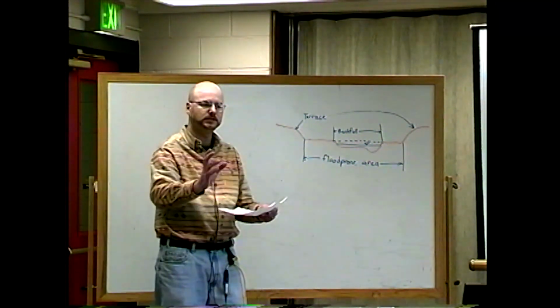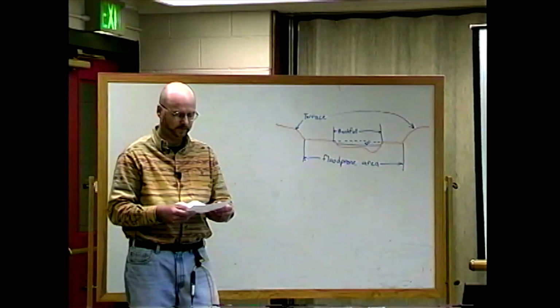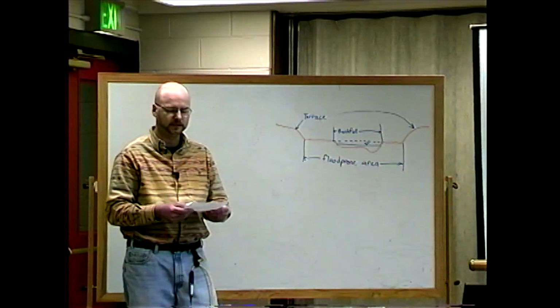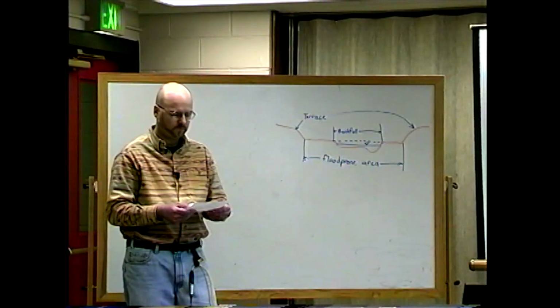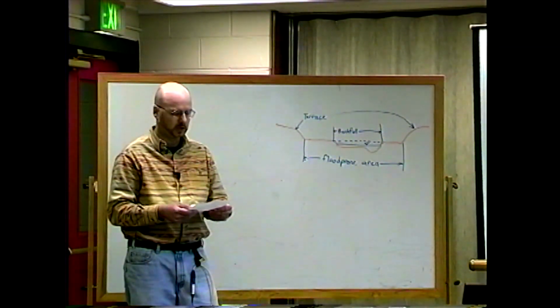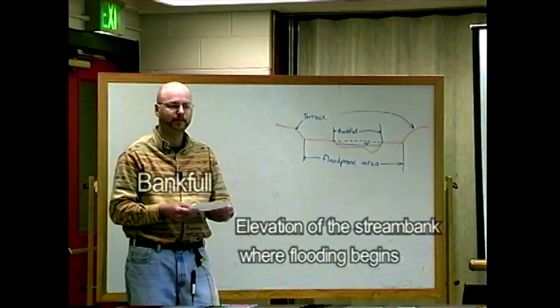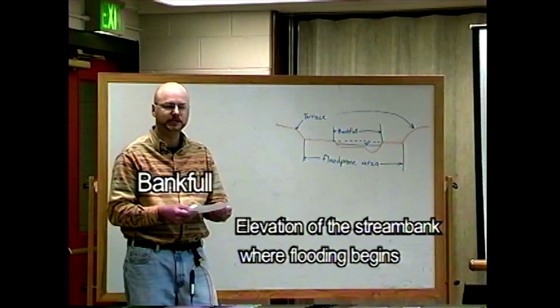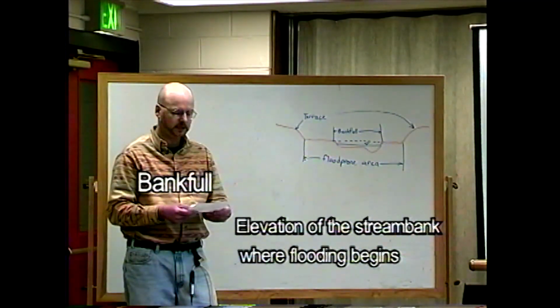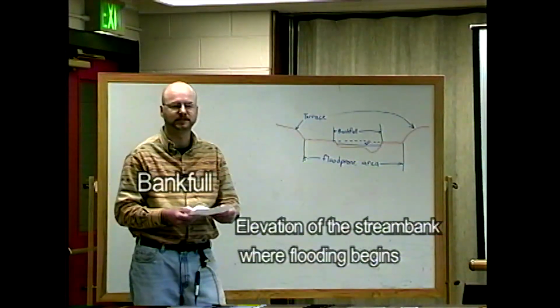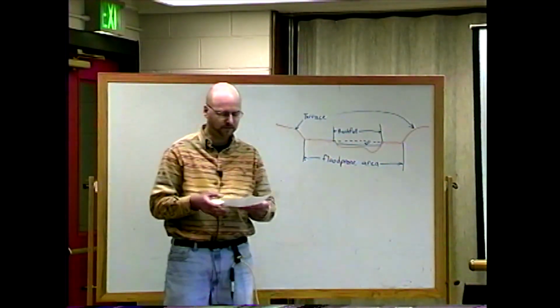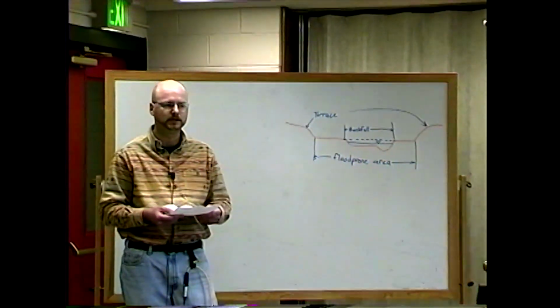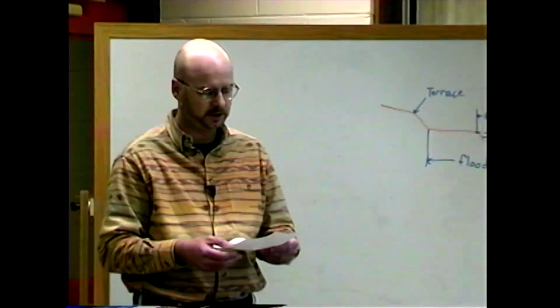It maintains the form of the channel and is the most effective discharge at moving sediment, forming or removing bars, forming and changing bends and meanders, and generally doing the work that results in the average morphologic characteristics of the channels.